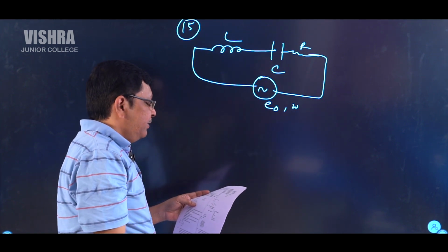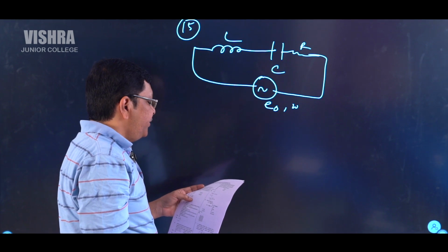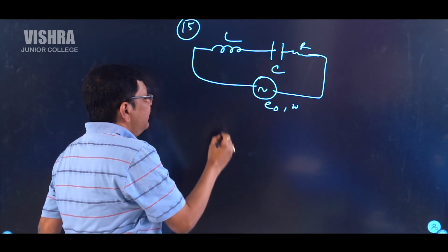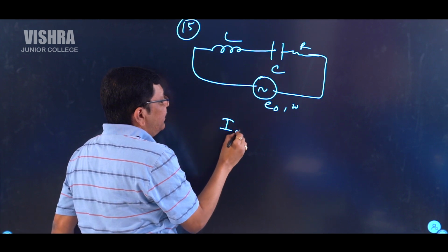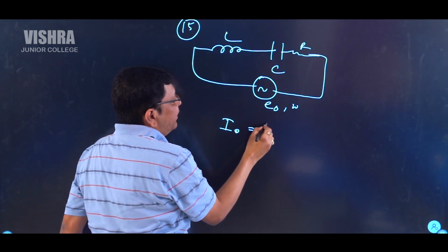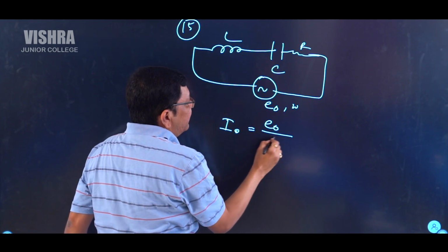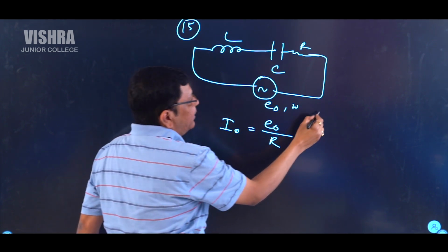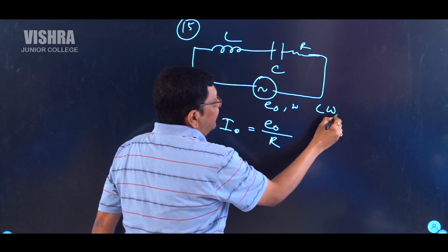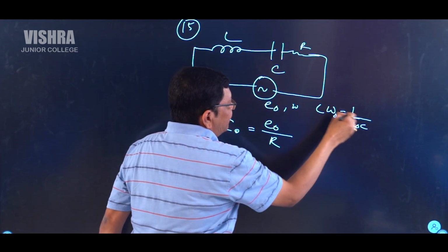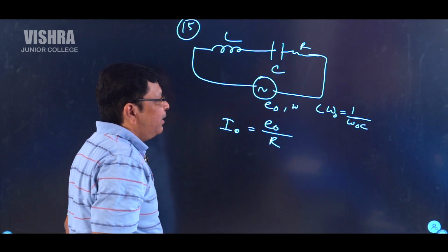He said the maximum amplitude of current is I0 when the resistance is R. Here the current amplitude I0 will be maximum when the impedance is minimum, and the minimum impedance of the circuit is R, because this happens at resonance. At resonance we know L omega naught equals 1 by omega naught C. So they balance and the impedance will be R.